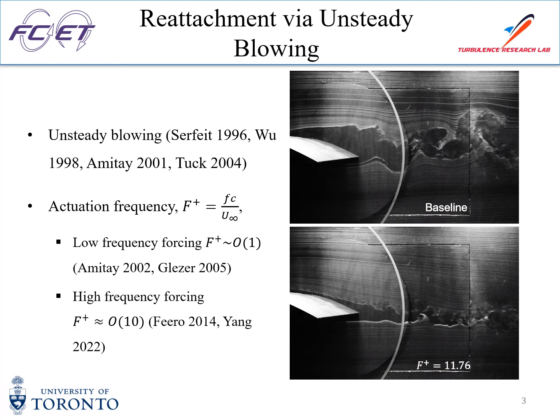The actuation frequency is often non-dimensionalized as F+, which is the frequency of the blowing times the chord length of the airfoil divided by the free stream velocity. Actuation frequency on the order of 1 is commonly known as low frequency actuation, whereas on the order of 10 is often known as high frequency actuation. As I will show later, these two frequency ranges have different effects in the flow reattachment.